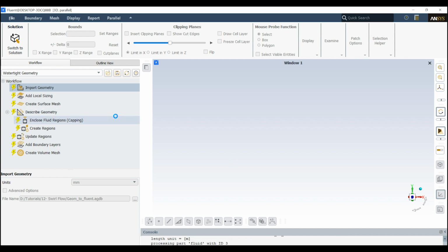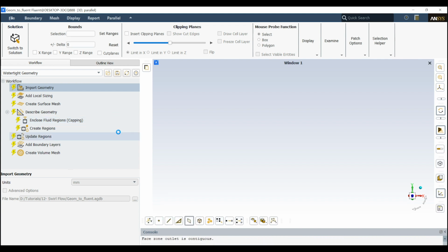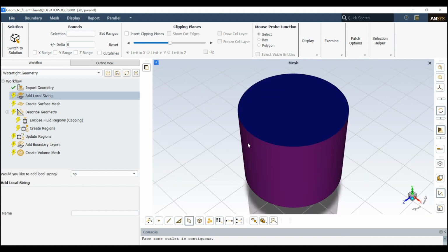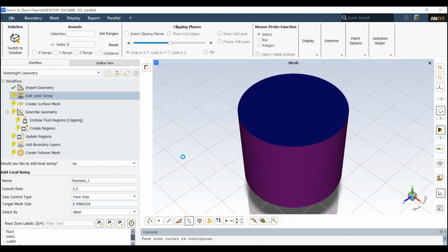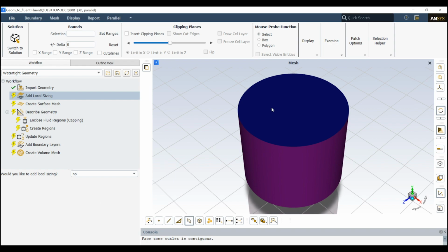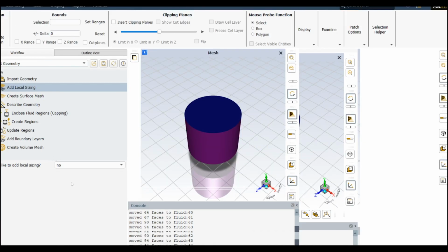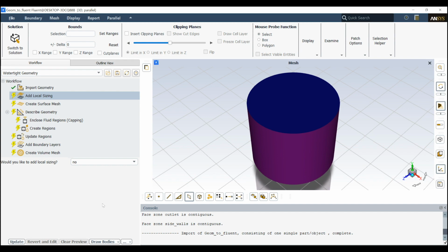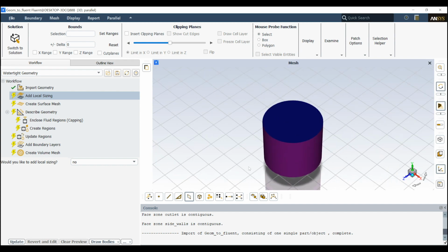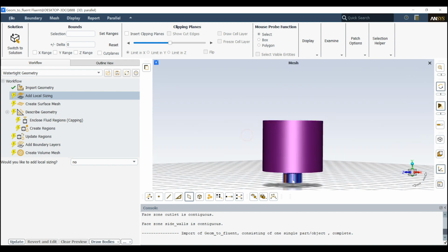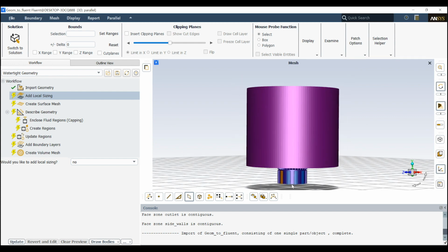Fluent meshing is getting better these days. Personally I use the Fluent meshing more. I encourage you to also use the Fluent meshing more, especially if you are new to CFD and just getting started with CFD. With ANSYS Fluent, it's easier to get a better mesh.